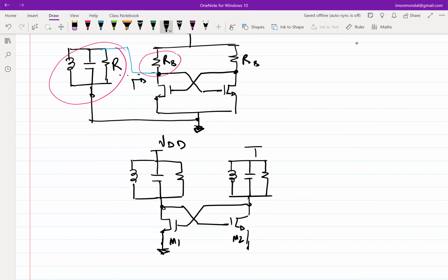Another reason we want to do this, I mean, one might say that this is probably not a very good idea because you are doubling the size of the inductor, which is correct. But one of the reasons you would like to do this is because differentially, if this goes high, this goes low, you get a differential output for free. And as you must have seen in other circuit courses, differential circuits have a lot of advantages, right? In the sense that they can give you some noise immunity with respect to coupling. It also gets rid of second harmonic distortions, right?